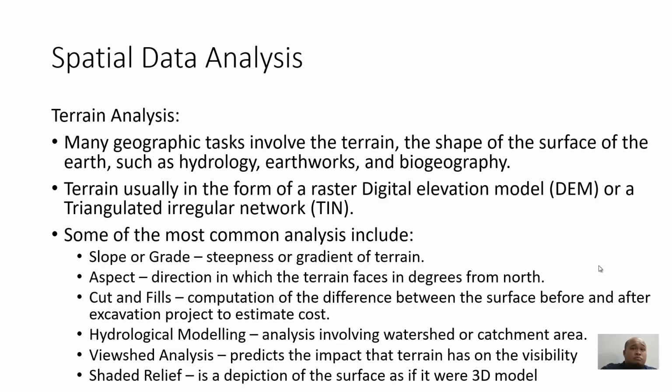This is familiar, especially for engineers, civil engineers. Cut and fills is the computation of the difference between the surface before and after the excavation work or the excavation project, just to estimate the cost. Right. This is very important for project managers to study the budget before any construction works even started, right?